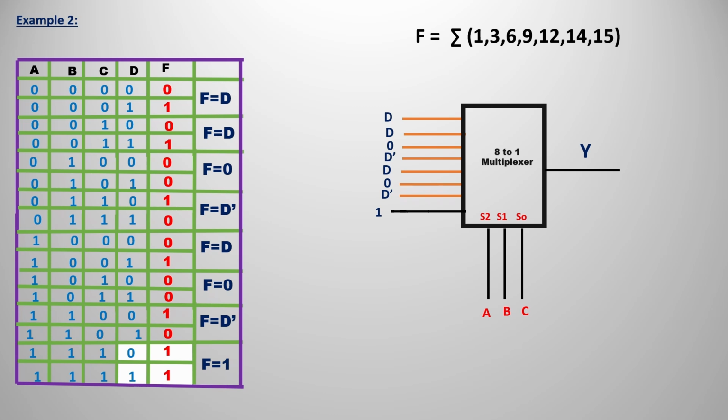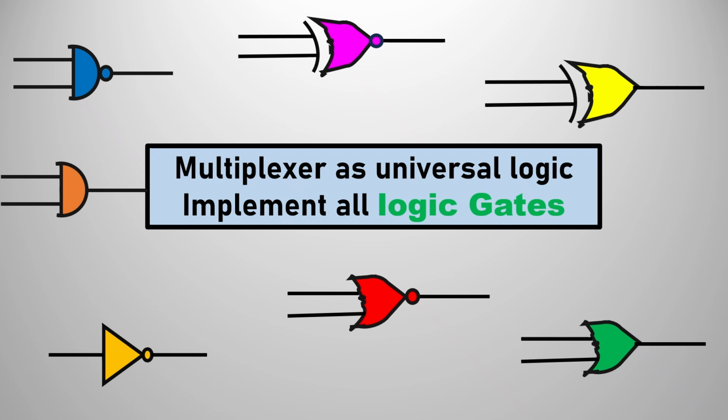So you can also see in the 8x1 multiplexer that I have represented D7, the last one. If you send ABC as 1 1 1, the final output would be D7. So what is our D7 in terms of D? That is 1 only. We do not have any relation. We just have the output, that is 1. I hope you understood the second method very well.